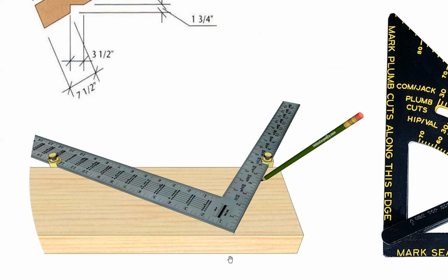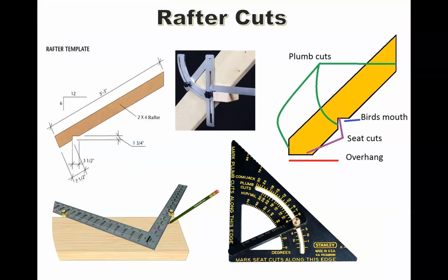Now, let's imagine that you take that piece of board and raise it up into the air so that the edge that is cut is plumb to the ground, like this drawing here. If you raise the board until the cut edge, where the 6 inches was, is plumb to the ground, then the angle of the top edge would be 27 degrees.